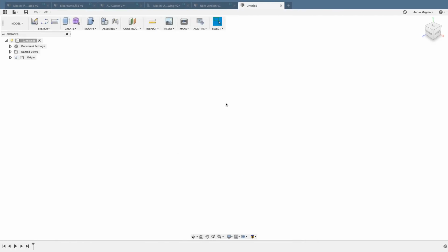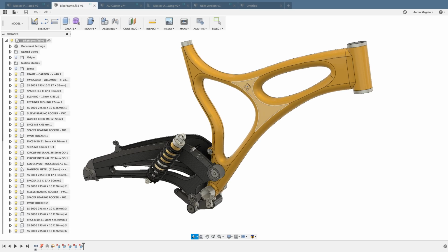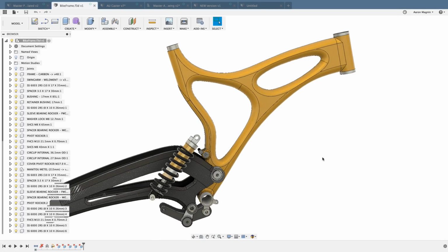So jumping right back into Fusion 360, let's just open one of these files that I have open here, and you can see obviously this is shaded with edges right now. So if I wanted to, I can use that keyboard shortcut of Control 4 to go to maybe just shaded, which I would recommend a lot of the time if you're working with a very complex file. If you just use shaded views, it cuts down a lot of the computation, a lot of the lag that could happen if you're working with the complex file. So that's an important one to use. I'll probably be using Control 4 and 6 to turn my edges on and off, but of course you can go to all the different types as well.